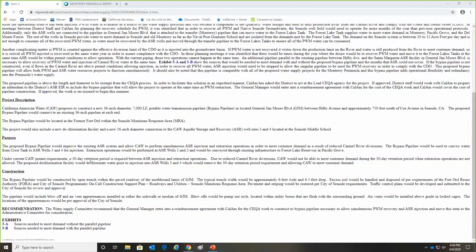The water goes into the aquifer, and then the chlorine breaks down into a couple of different chlorine breakdown byproducts, which takes a time window of about a month to sometimes 6 weeks for the disinfection byproducts to be consumed by the microbes down in the aquifer.